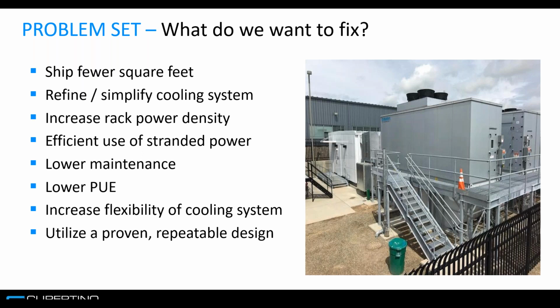We want to refine and simplify the cooling system. Udi's point about direct on-chip, on-demand, and instantaneous on-demand of the cooling without any control points was, again, very attractive to us. We're able to increase the rack power density, make more use of stranded power in brownfield installations, significantly lower the maintenance of our modular data centers, lower PUE, and increase flexibility of the cooling system.